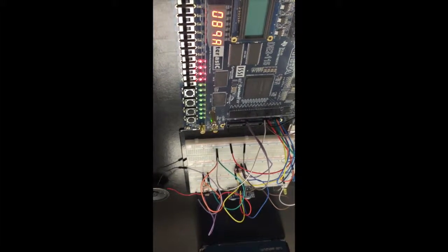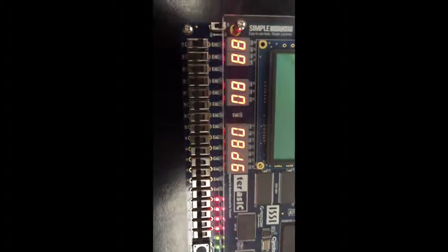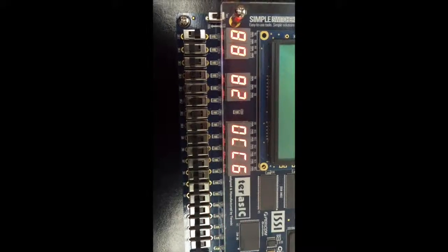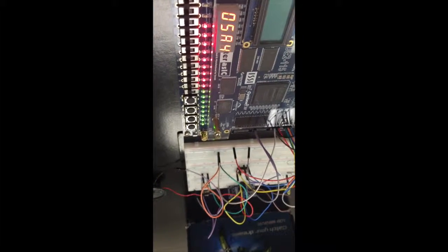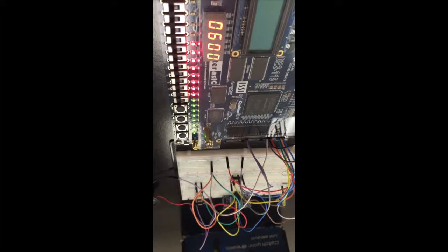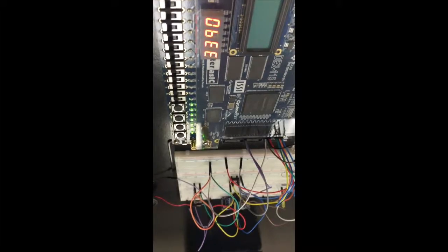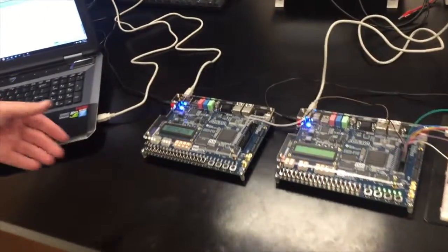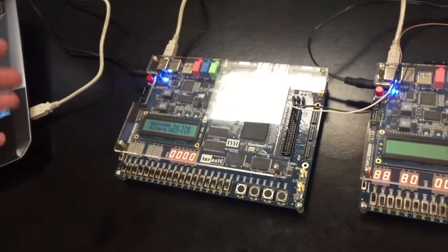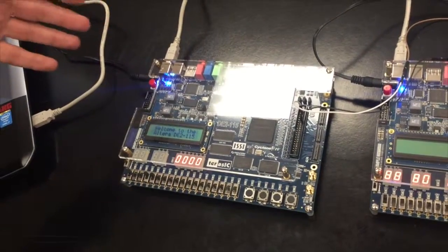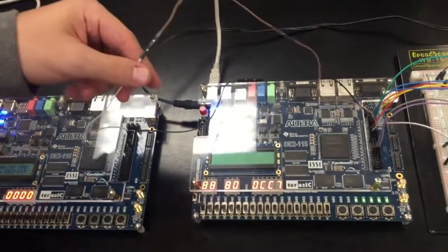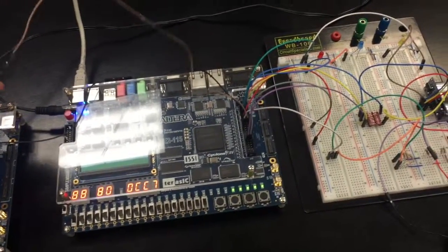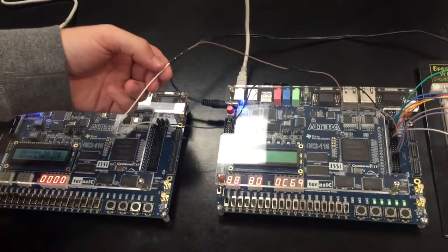The alarm also displays the distance on the hex display. As the object gets closer to the sensor, the distance decreases on the hex. On the other hand, as the object moves away from the sensor, the distance increases on the hex. This is the control FPGA. It controls what state the system is in at any point in time. It specifies to the alarm system what state it's in using this GPIO line. If it's inactive, a 0 is sent over this line. If it's active, a 1 is sent over this line.